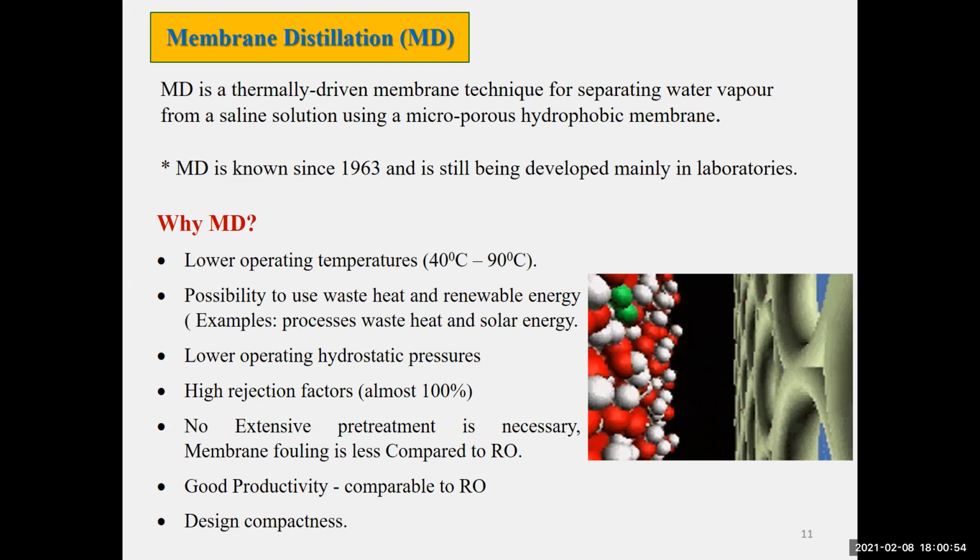We take this heat to heat the water, and then hot water passes by the feed side of the membrane and evaporates. You take the vapor, condense it, and you have sweet water. So any low-grade energy source that brings us a temperature between 50 to 70 degrees centigrade is a system that we are going to consider.